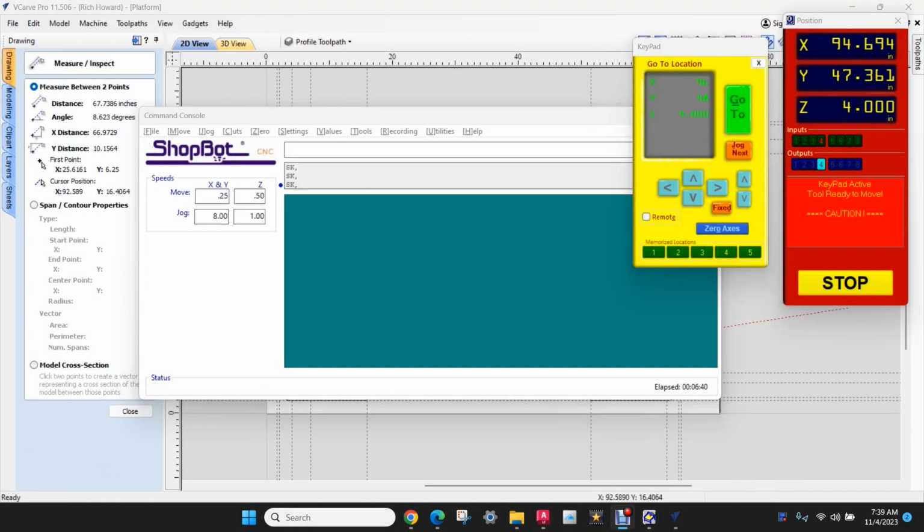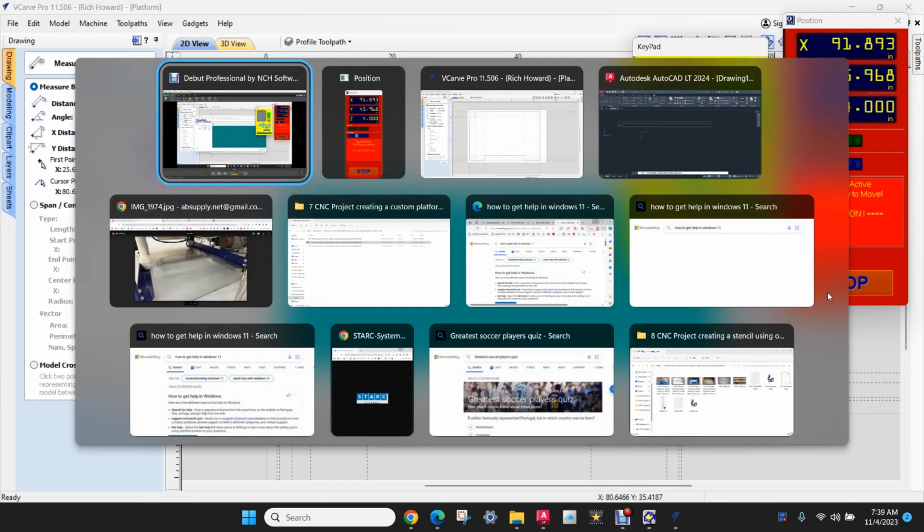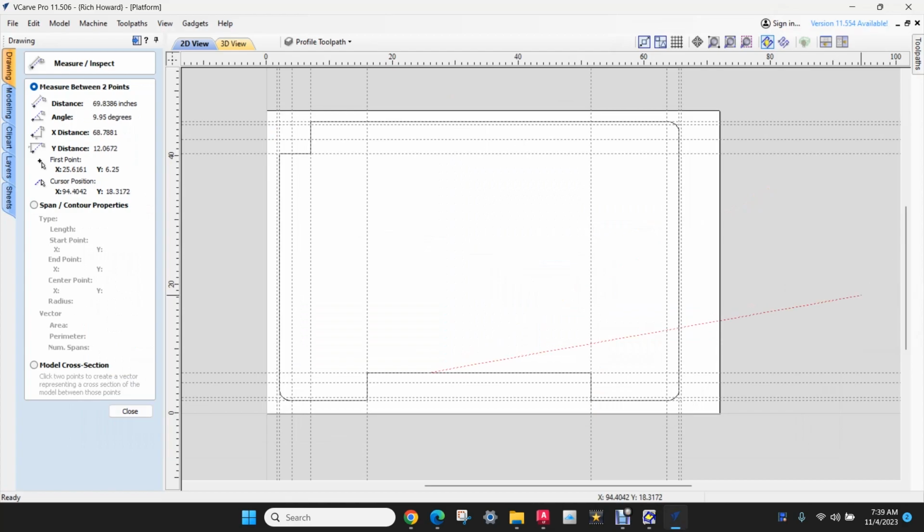I've added grease to the rack on the tool, and I'm very slowly moving the machine to get the grease spread around. Yeah, so now it's at a stop. So now what I'll do is move it back down 1, leave it at 4. I have so much material thickness on the bed. I'm just very slowly moving the machine to get that grease spread around, to the point where you forget it's running. So you can Alt Tab while it's running, which I'm not recommending, but you can Alt Tab to a different program.